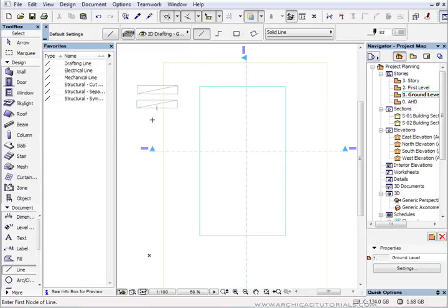Now I'm not saying this is the way to do it, but I'm just trying to illustrate that you can actually model a light up so it looks beautiful and perfect in 3D. And if that's what you want to do and you're going to get paid for it, by all means do it. But if you're not, just do the same thing, and that way you can guarantee that you'll get work out quicker than if you were working in straight 2D, because it would have taken about the same amount of time, but it will also now appear in all sections and elevations. An ArchiCAD drawing will increase in size dramatically if you use 2D lines, but if you use 3D objects, the actual file size will stay smaller as well.